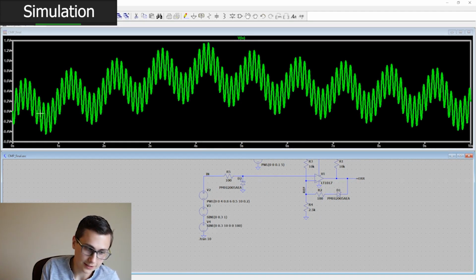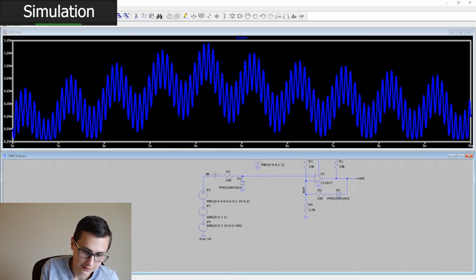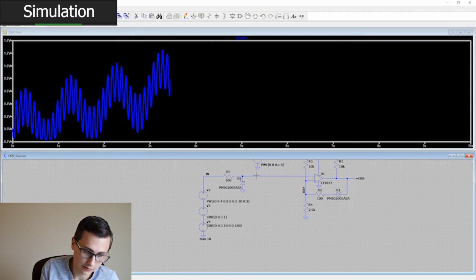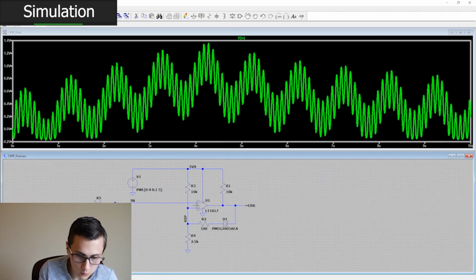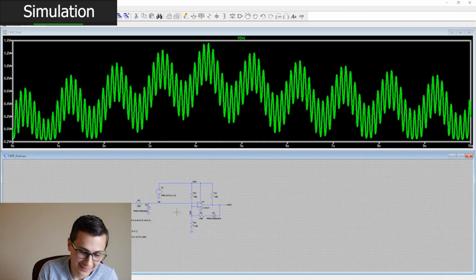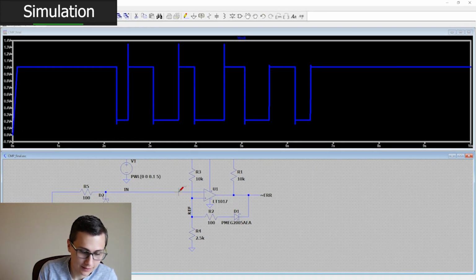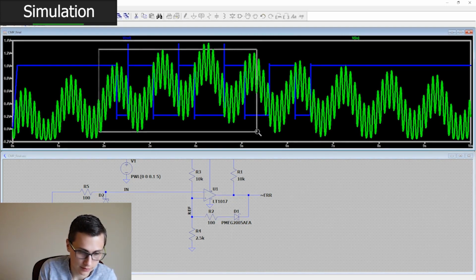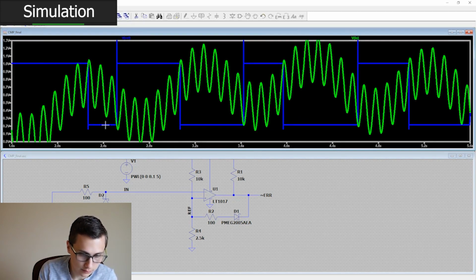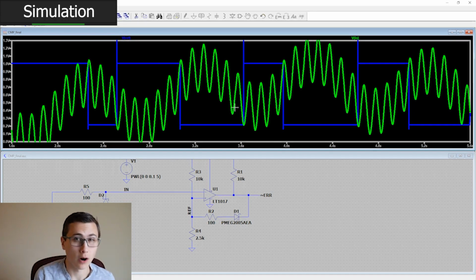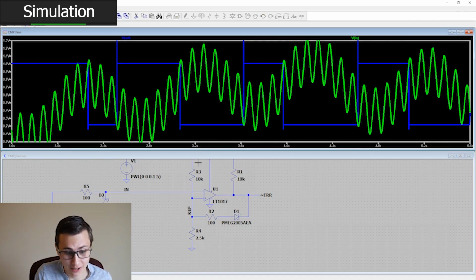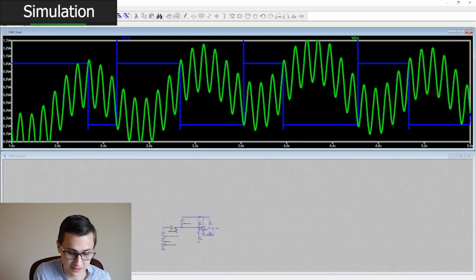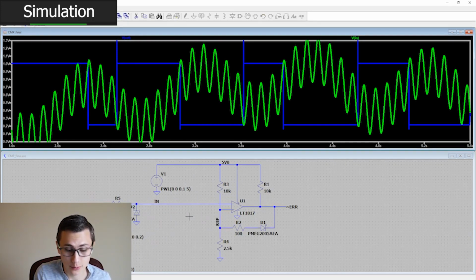Okay. Hey, look, we don't go negative a whole bunch anymore. So you can see what we're doing is we're just clipping off that negative part of the waveform. Everything's fine. Okay, the point that I was trying to make: this is not close enough to 0, right? We are able to retrip this comparator. For our application, this was close enough because our threshold was closer to 2.5 volts, and when you go from 2.5 to 0.2 or 0.3, that is quite a lot. An order of magnitude on your threshold for hysteresis is pretty excessive.